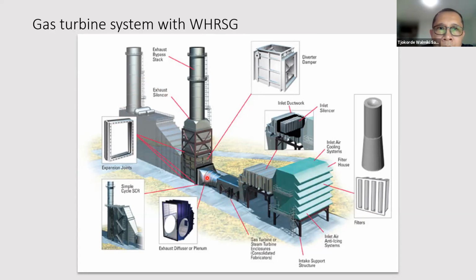Okay, and this is the exhaust bypass. In normal operation, this only allows a small amount of exhaust gas, or is even closed totally. There's a flow diverter here that directs the flow of hot gas, and this one is the boiler, this trapezoidal shaped box here. So this is the steam boiler that utilizes the heat from the exhaust gas to produce steam. Okay, so pretty nifty.